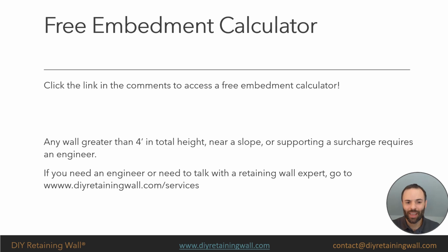And as a note, any wall greater than 4 feet in height that's near a slope or supporting a surcharge requires an engineer to review it.